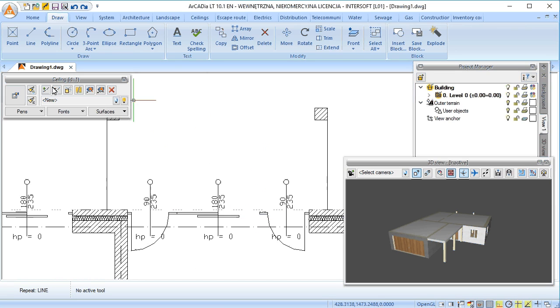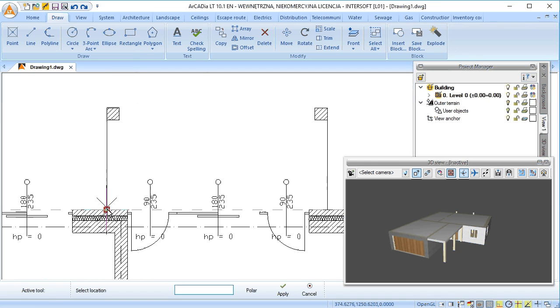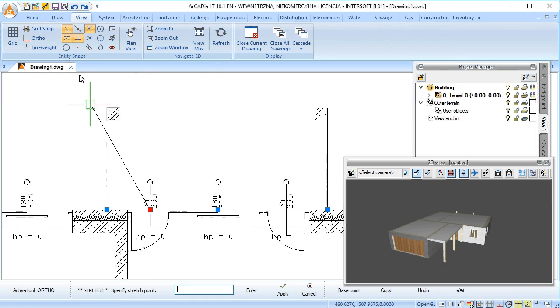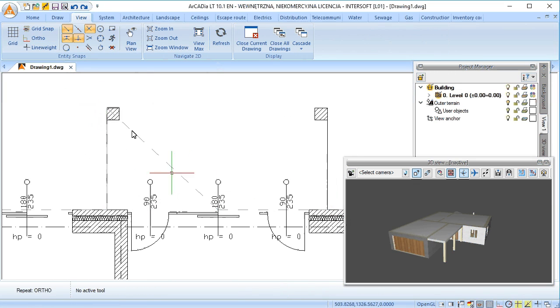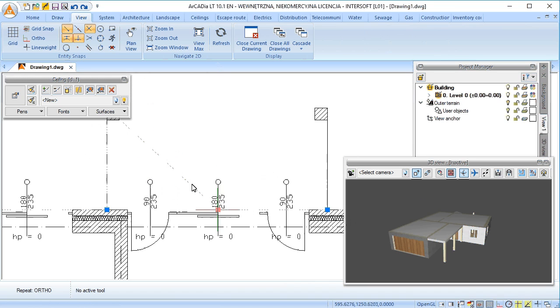We are selecting the ceiling and the Add Point option in the action bar. On the outline of the ceiling, we are selecting 4 points that will become the new corners. We are terminating the command with a right-click. We are selecting the ceiling outline and moving 2 grips onto columns, thus creating an overhang over the ground floor.